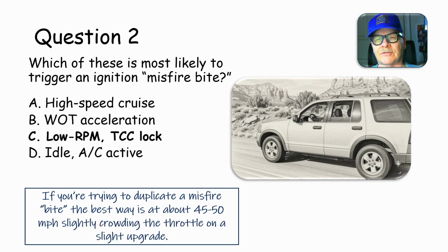When you're pulling a light grade and you're crowding the throttle just a little and keeping it in high gear with a torque converter lock, that's when you're most likely to feel a misfire. Now, I worked on an old '65 or '66 Mustang one time that a guy brought in that had been totally restored, had a 289 in it, and he wanted a tune-up done by the best guy in the shop.